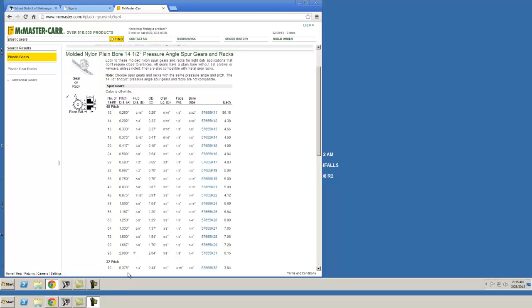So what I'm going to do, I'm going to sketch on that surface. Sketch a boss here. I'll put that dimension. Oh, for some reason it looks like I'm in metric units. Let's exit out of here, exit out of there, and make sure that it says custom down here. I should be inch pound seconds.